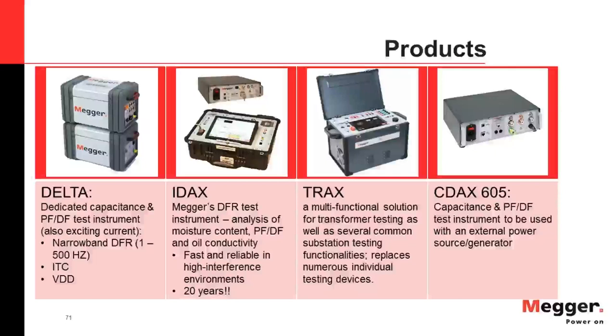And finally, for the most demanding applications, we have the CDAC to the far right, which is a very high precision instrument designed for laboratory, production line, or even field testing of electrical equipment installation and insulating materials, as well as, for example, calibration of CCVTs and other ratio devices.